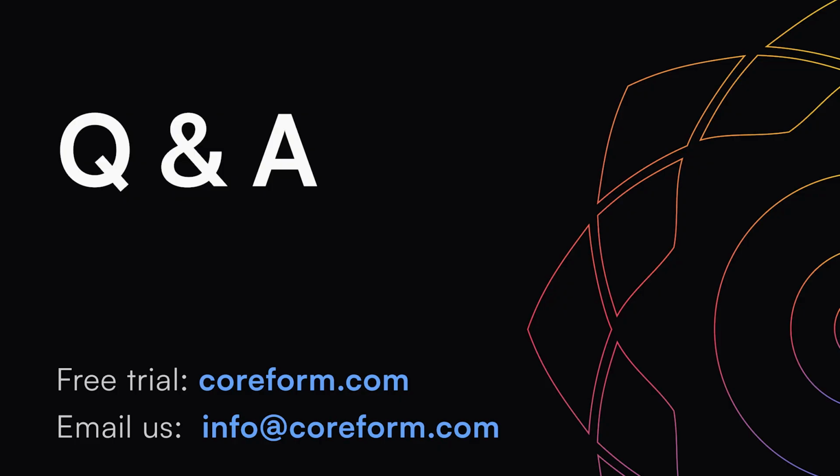So probably the biggest limitation today for those kinds of problems is that in the current release, the global refinement approach means that if you want to refine to get accuracy, you have to globally refine your solution, which means you're refining in regions that you don't really care about. The solution to this is local adaptivity. And really, in my experience, continuity has no ill effect on your ability to approximate the solution when you consider solution accuracy per degree of freedom. And again, degrees of freedom are what show up in your linear systems.